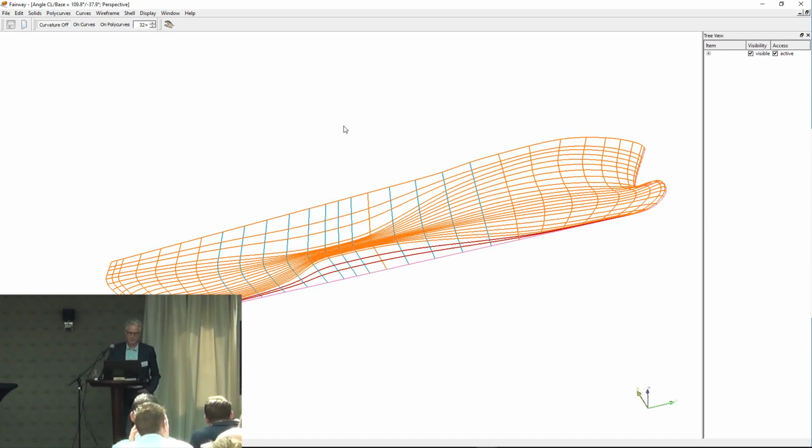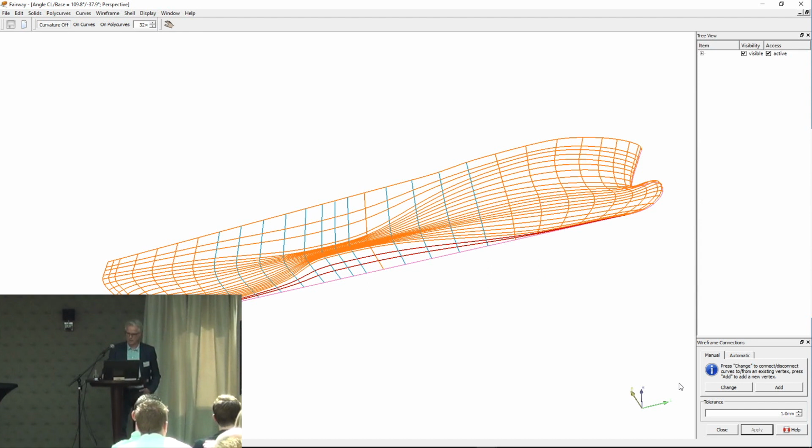However, this is only a wireframe. So we did not import a surface. We imported lines that together will constitute a solid model when I'm done. And what will that take? I can use the wireframe option to generate wireframe connections. First, I will increase the accuracies a bit.